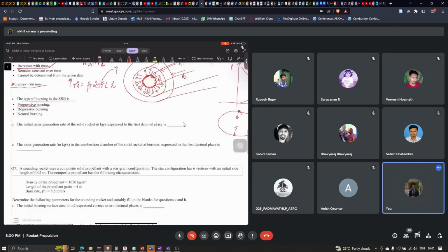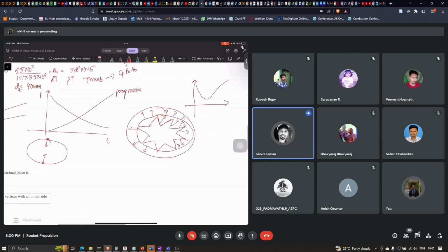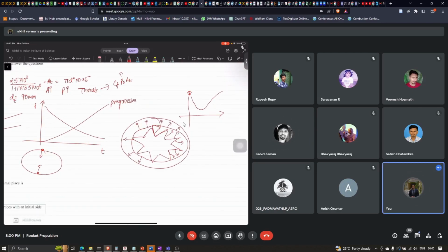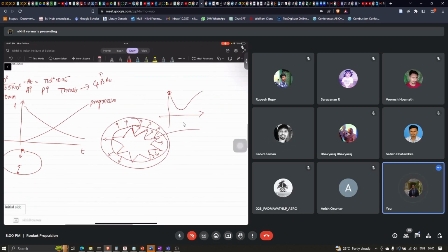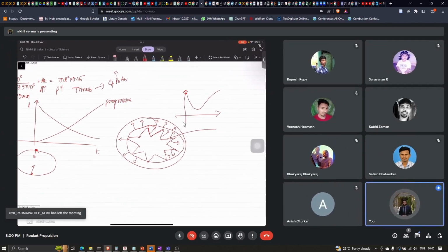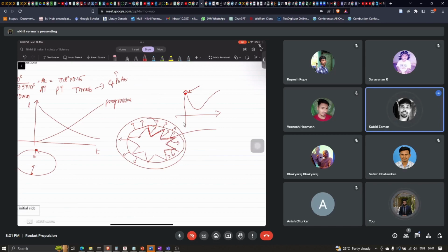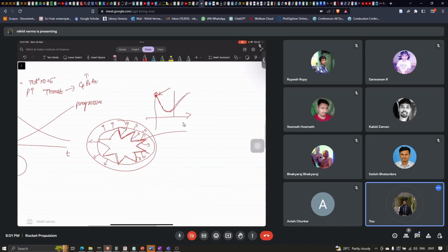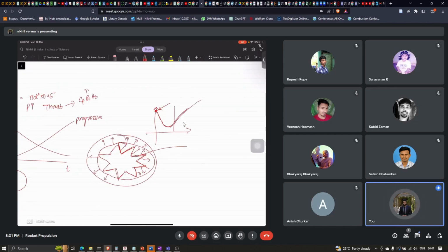So it will decrease up to the vertex, up to the point the burning ends. Initially at the vertex, it will be very high. This type of thing is used in real rocket engines, where you need higher thrust in the starting, because your initial mass is more. If you increase this area so that the pressure increases rapidly, and you have a thrust, then you can decrease. Then further you can increase when you have left the dense atmosphere, then you can accelerate faster.